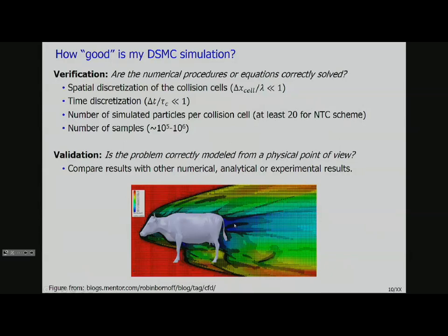The mesh is much simpler. So even if you set a really bad mesh, you'll still get a result. But if you don't follow these spatial discretization parameters, you'll be violating some fluid properties, but the simulation will still run. You just have to look through the results to make sure that they're right. Does that answer your question? Perfect, thanks.